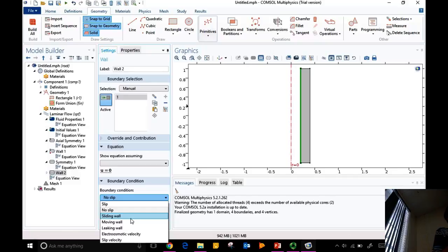I strictly think that it is still no slip, right? A sliding wall, but the fluid sticks to that sliding wall. So there is no slip between the fluid and the wall in a strict sense, right? That's why the fluid moves with the wall. Okay, but in their terminology, no slip means velocity is 0. Velocity difference 0 is a more precise way of saying it for no slip condition.